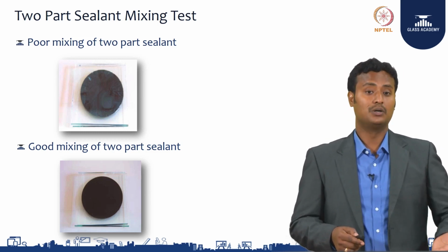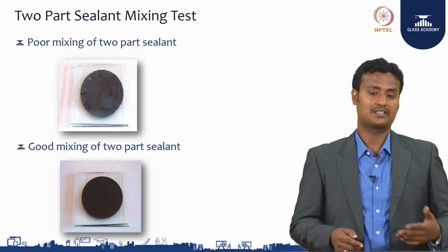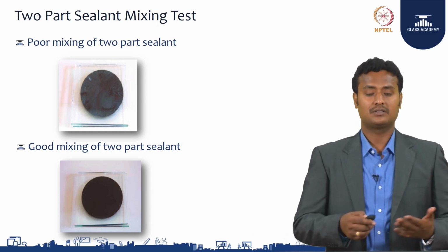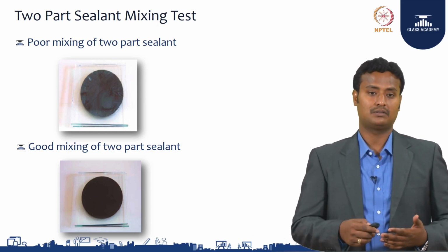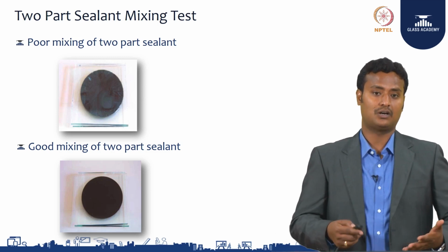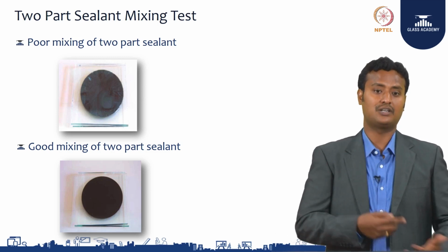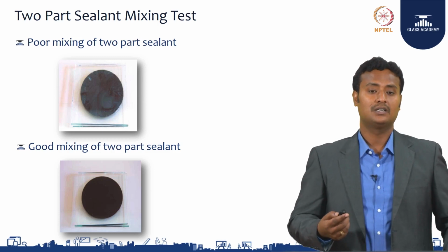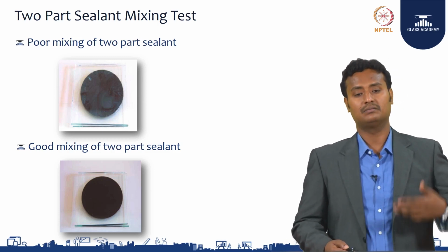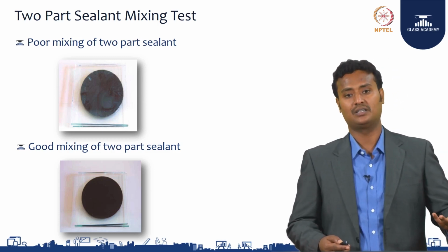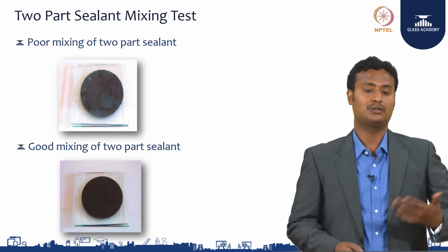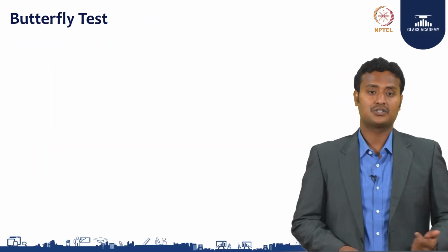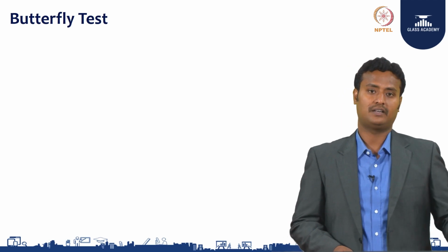After that you can do an adhesion test also. If you keep it for a couple of hours, for example 8 or 10 hours, and you try to remove it and are not able to, the adhesion is proper. So not only the mixing ratio, you can test the adhesion here also.